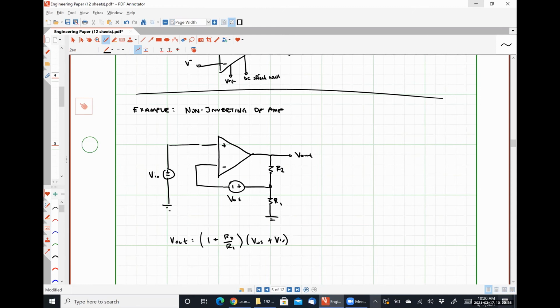No, not even a little bit, right? We could say that this voltage Vx right here is equal to Vout times R1 over R1 plus R2, and it is also equal to VOS plus Vn, and do an arbitrary amount of algebra and get the exact same result. That is why it literally does not matter if we refer the voltage to the inverting input terminal or the non-inverting input terminal. Doesn't matter what polarity we use, the effects are going to be the same.